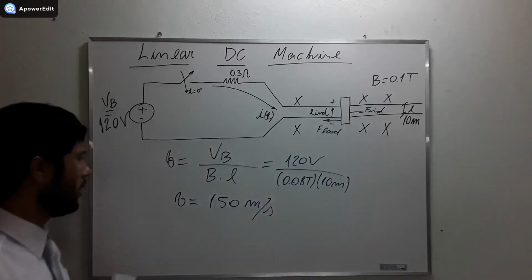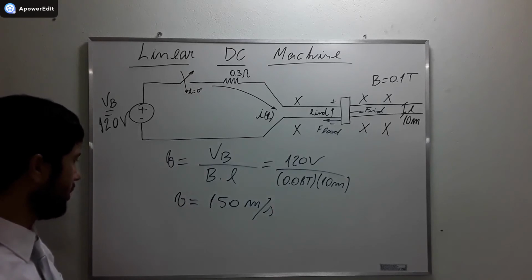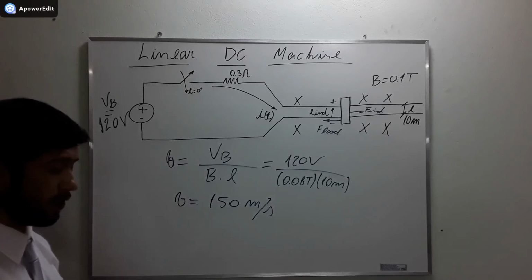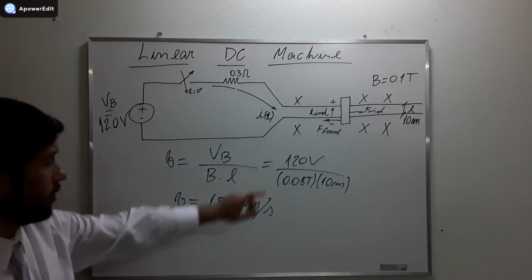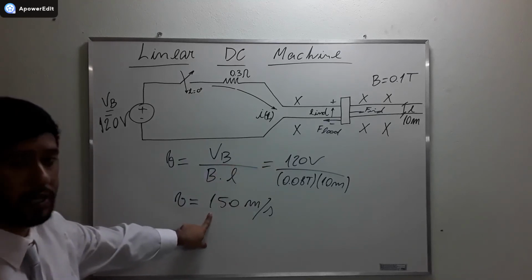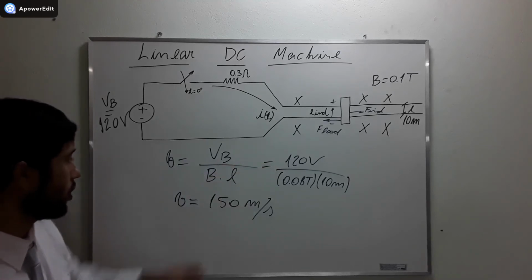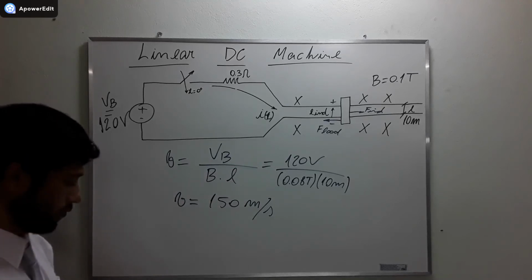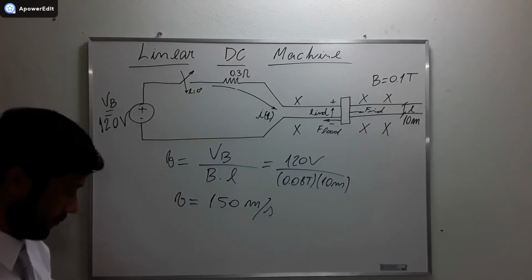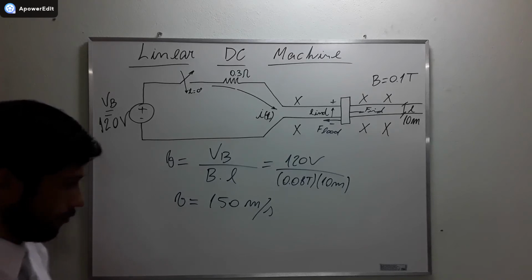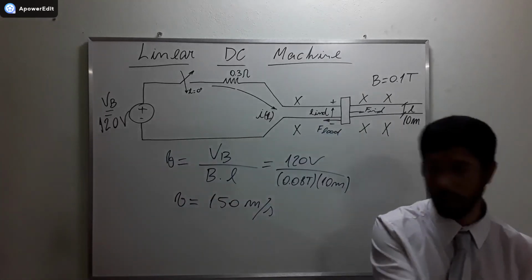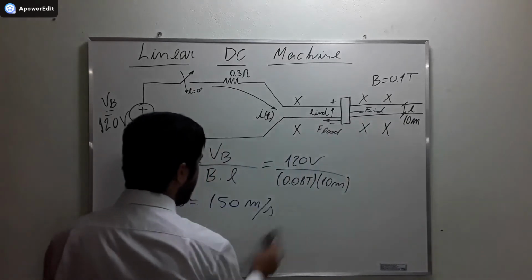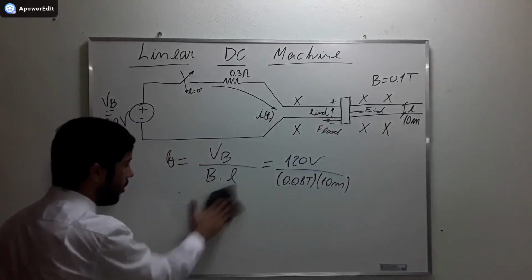Okay? So this is an interesting property of DC machines. If you decrease the magnetic field, actually the machine accelerates. Okay? Very good guys. Now to finish, let's go to letter D. Letter D, the machine is going to work as a generator, not a motor anymore.